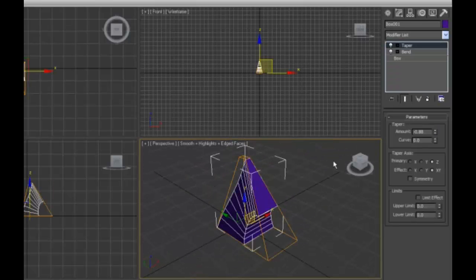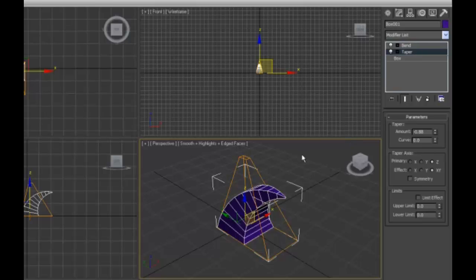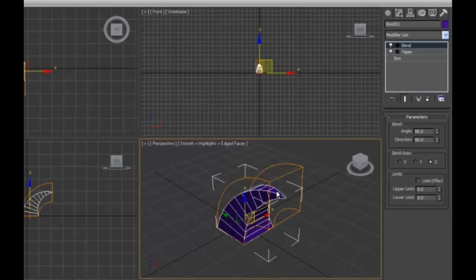This is an object where you first apply the bend modifier, mainly first you bend your object and then you taper the object. Whereas if you reorder the bend and taper, you first squeeze one end of the object's vertices to merge with each other, or essentially get closer, creating a pointy shape, and then you apply the bending to this object.